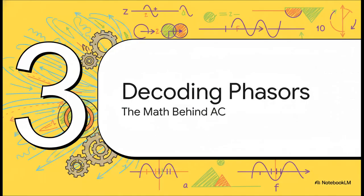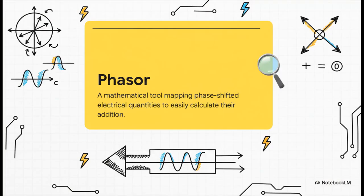Okay, part 3, decoding phasors. Enter the phasor. Now, what is that? It sounds like something out of a sci-fi movie, but it's really just a mathematical tool. It takes complex phase-shifted electrical quantities and maps them out geometrically. Why do we do this? So we can easily calculate their addition. In fact, in a perfectly balanced three-phase system, calculating the vector addition of these phasors results in exactly 0, which, by the way, is exactly why a neutral wire often carries absolutely no current.